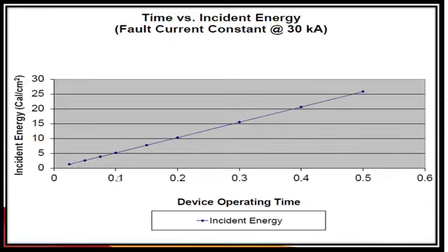You will check the device coordination and the clearance times, and you will ask your consultant to do the protection coordination and reduce this to a value that won't cause nuisance tripping to the network. The network is reliable, but the incident energy needs to be lower.